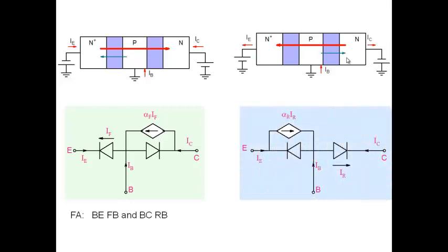So what we get is a circuit like this. Two diodes again, as usual. This is the diode which is forward biased now. As it is forward biased, a current IR flows, and a fraction of this current flows across this particular junction, this red one here. So this current that you see here is what is coming here. And of course, it's a reverse bias diode, so its own current would be very small. So here is a forward active mode, and here is a reverse active mode.